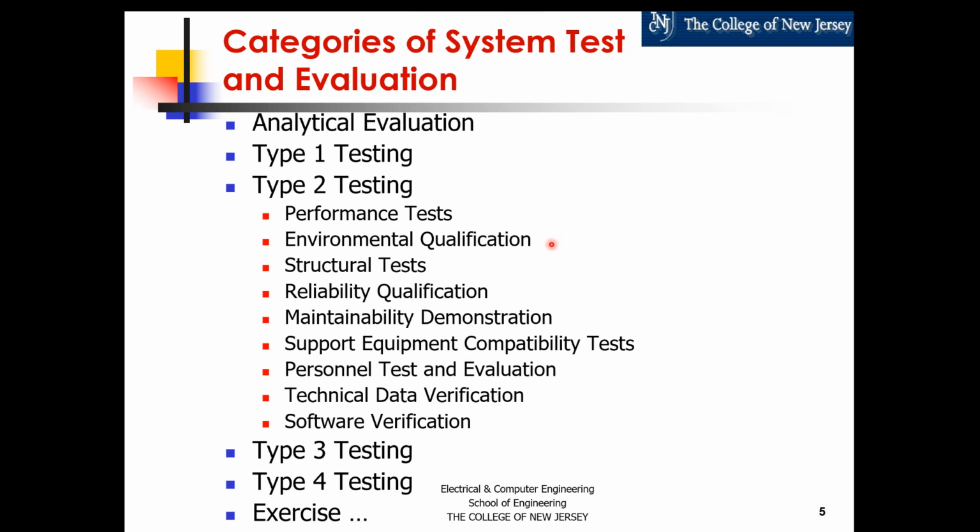A lot of these tests are destructive in nature, because they stress the product beyond what you designed it for, but they also have the capability of accelerating the life of the product. By exposing the product to these stressful conditions, you can see if the product is going to last, for example, 10 years. There are many reliability models based on the materials that products are made of. The ones that I'm most familiar with are, of course, for silicon, with my semiconductor background. For example, if you increase the voltage and the temperature of semiconductors, you can simulate the aging of the oxides, and that will give you a measure